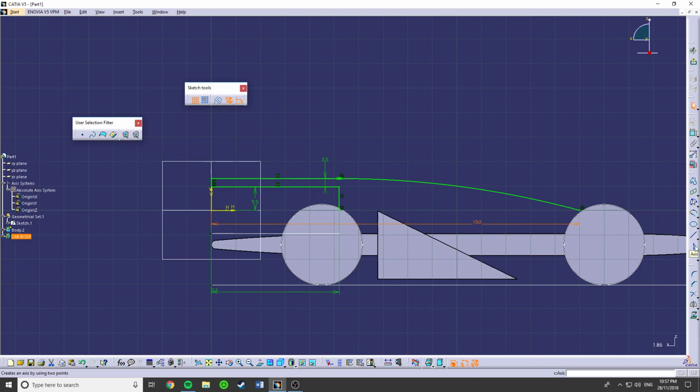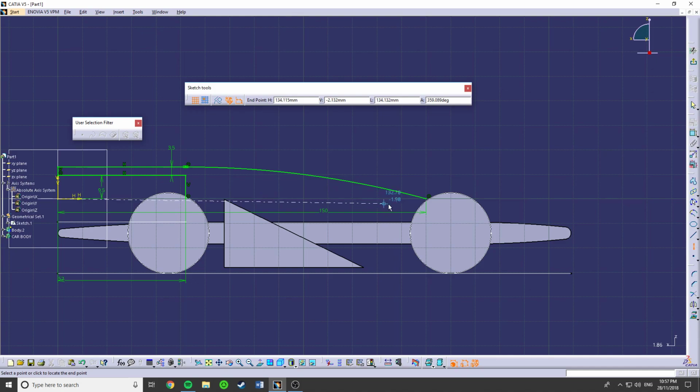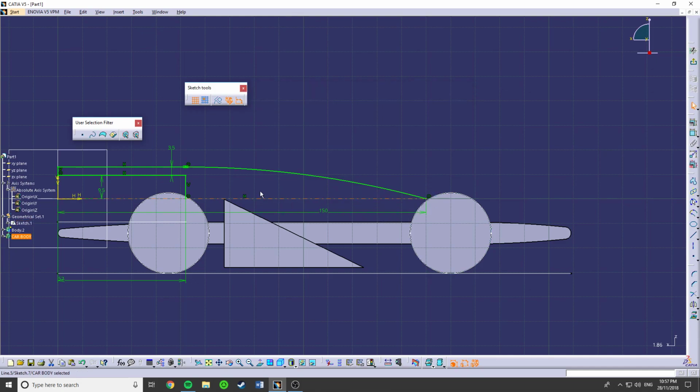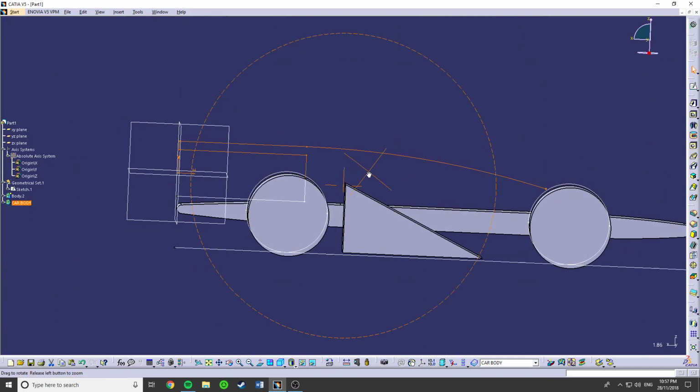If you see the axes tool up here, what we'll do is click around here, bring it around to the end, going from the start to the end. And this will allow us to revolve it around this axis here. You can also use the X, Y, Z axes in the axis system, but that's something to show you later.